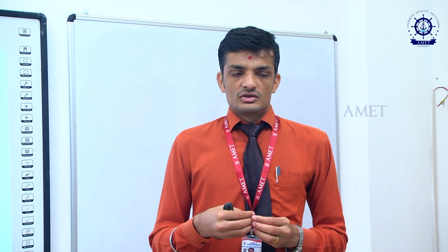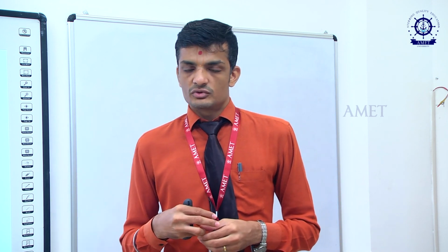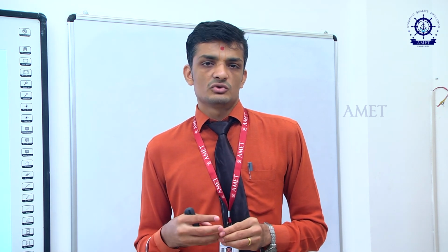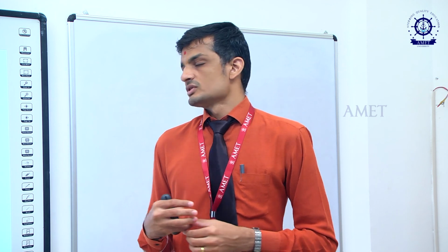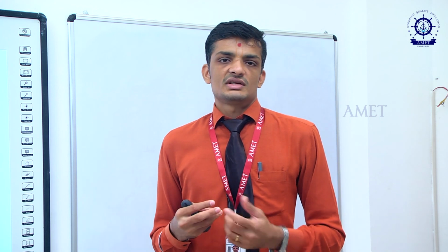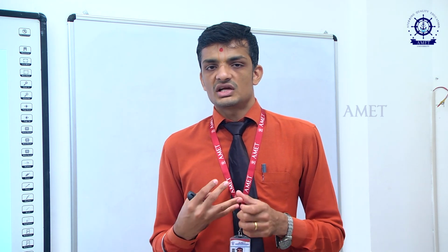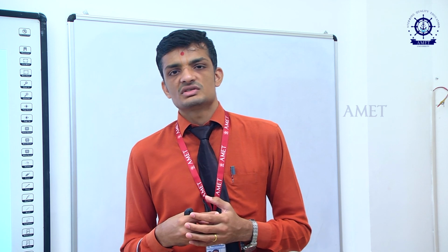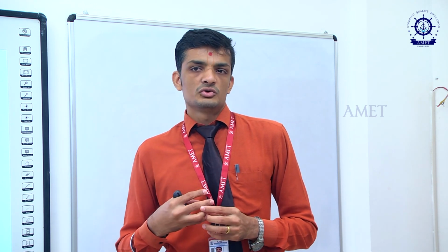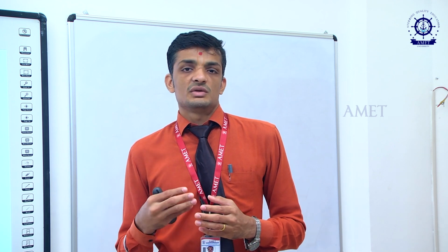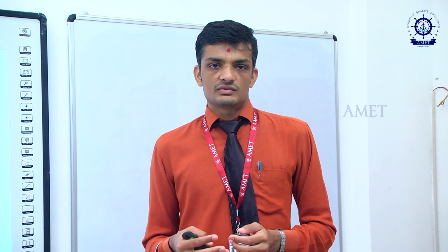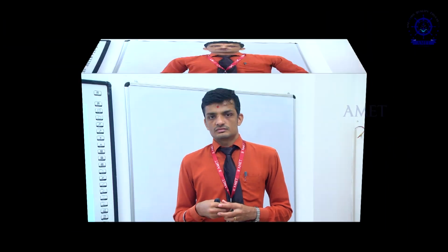Let's summarize quickly. What we discussed is the finite element approach, the main terms, what type of load, what type of structure it is, and the process of finite element analysis, right? So discretize the domain, select your shape functions, derive the element equations, merge all element equations and find the global equations, import the load vector, consider what loads you are going to apply, import the boundary conditions, and at the end you solve those algebraic equations. So this is how it is working. So that's the finite element approach.